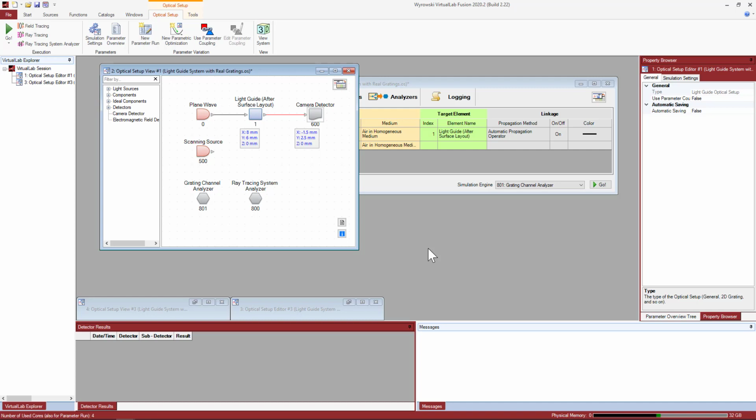So now diffraction is going to be included in the simulation. The simulation is going to take longer because those rigorous Fourier transforms are heavier to calculate, but it is a way of visualizing those diffraction effects throughout the system, and this can be caused by the finite size of the initial beam, and every time the beam propagating through the system hits one of those boundaries separating the different regions.